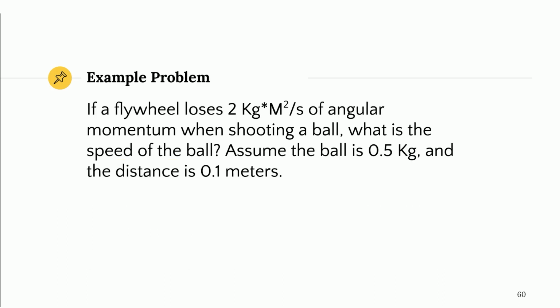So an example problem here is if a flywheel loses 2 kilogram meters squared per second, and that's the unit for angular momentum, when shooting a ball, what is the speed of the ball? Assume the ball is half a kilogram and the distance is 0.1 meters.